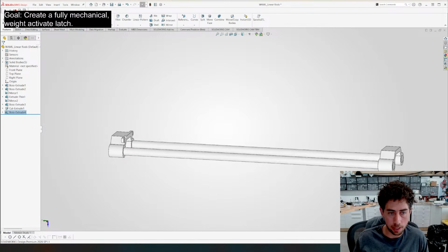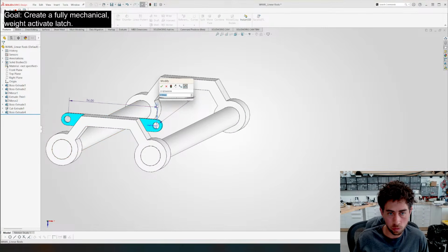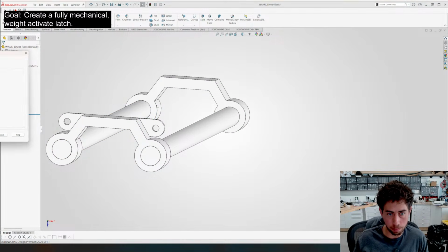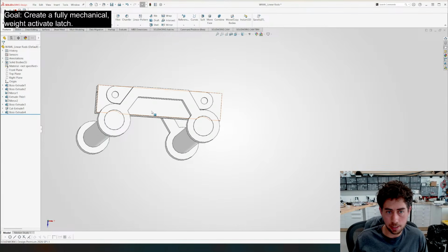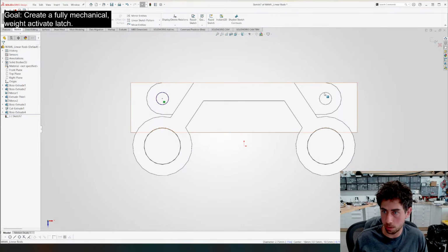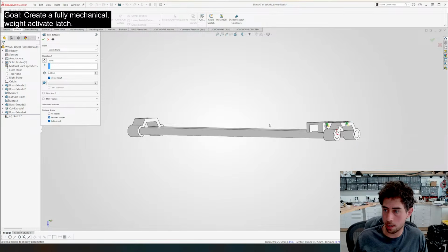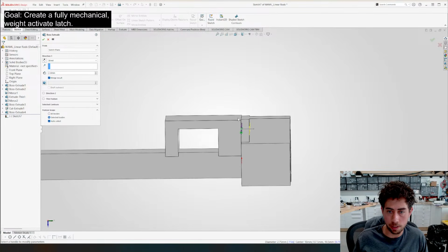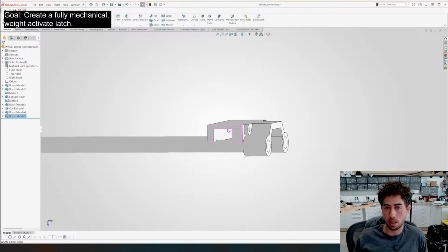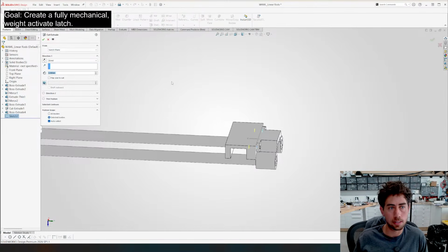Boom. Okay, so that's good there, but we're gonna make this a little bit higher. 3.5. I'll make it a little bit bigger. Boom. And now we got this, and then this we're just going to draw holes off of those holes like that and like that. And those will cut in, I think I made these walls 7, so we'll cut in 6. Okay, oops. What did I do? Oh, I made a boss, that's why. Make that a cut. There we go.